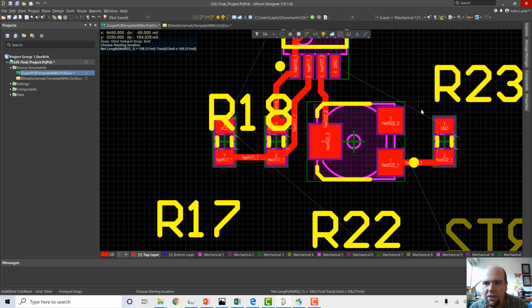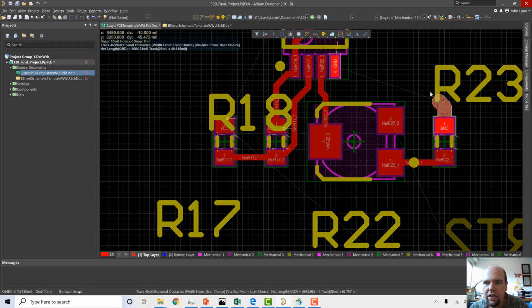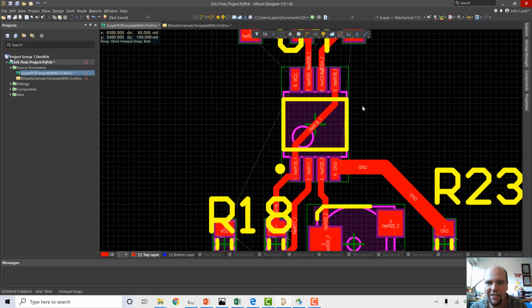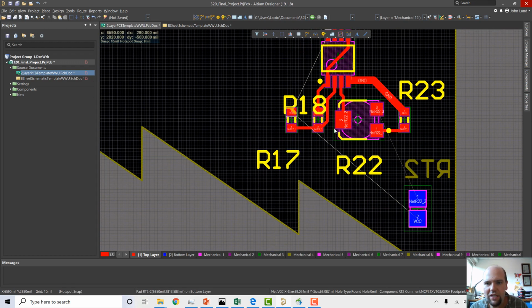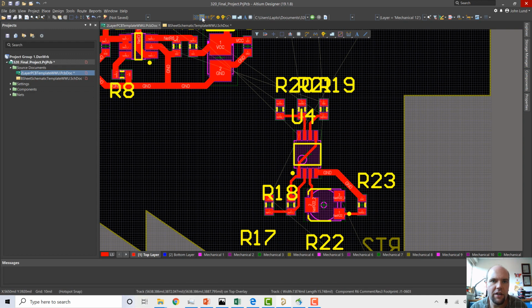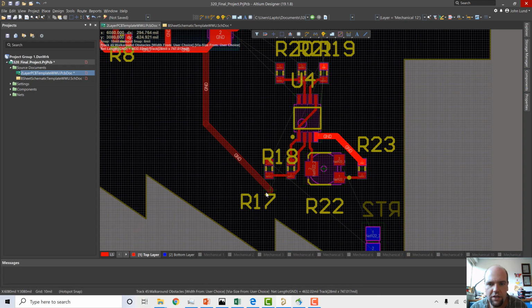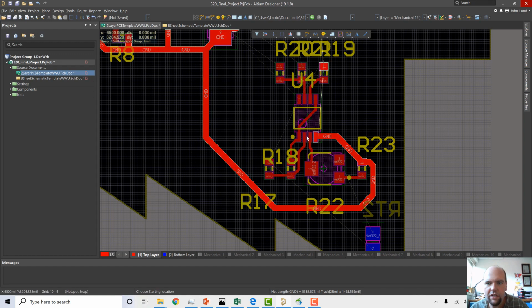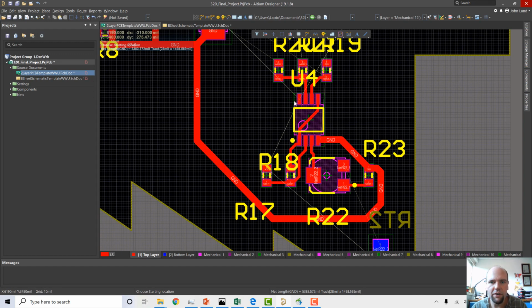So this pad connects to the thermistor, so it's going to have to punch over to the other side. This one's our ground, which is currently kind of thick here, which is fine. It's not necessary for it to be that thick. These connections are going to have to punch underneath eventually, but for right now, let's get to that ground bar down there. So let's pluck our ground here and move this thing around the trees. We're just going to wrap all the way around this one. Perfect, right? So that's a fairly low resistance. That's a pretty good connection to ground.